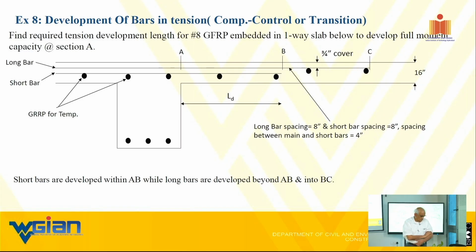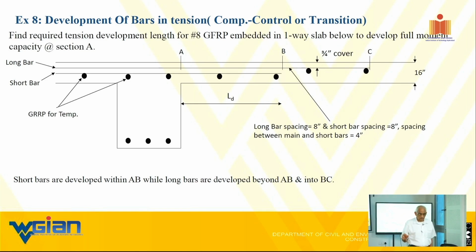Okay. How should I answer that? Wrapping undoubtedly increases not only the strength, of course strength increases much more, but also the stiffness. That is not because suddenly your concrete has somehow magically gone higher in strength. No, it is because of the confinement. Now, that said, I said also the stiffness increases.